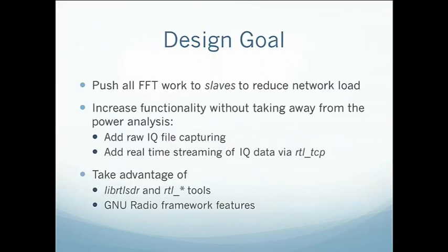The design goal was to push all the FFT processing back to the slaves, and then just transmit the power data back to the database and store it there, and then let the master query that database and find out what the nodes had found. Another design goal is to increase the functionality away from just doing the FFT and the power analysis to being able to say, okay, I see a spike, let's raw capture. So, I've added that support to it.